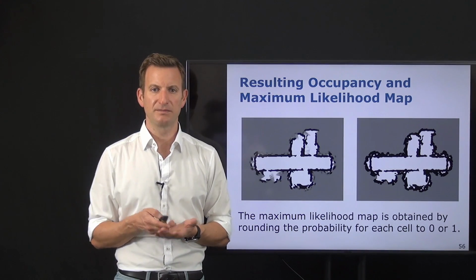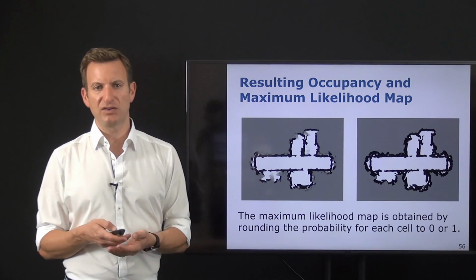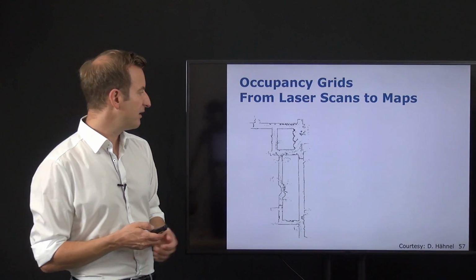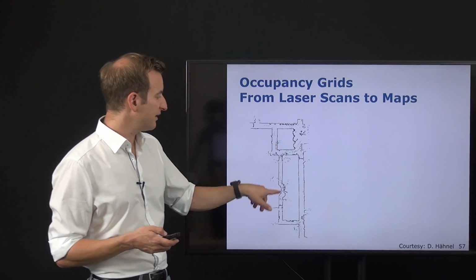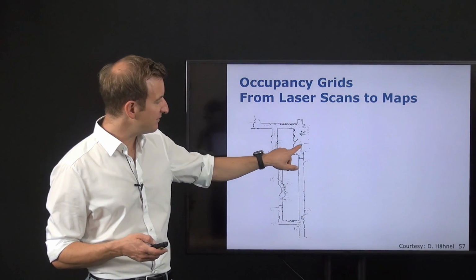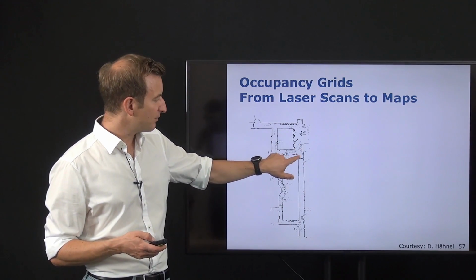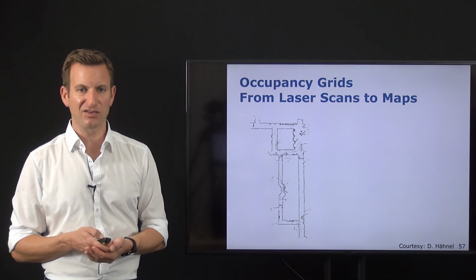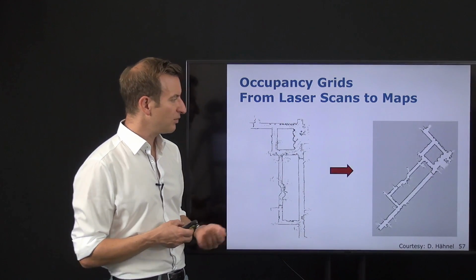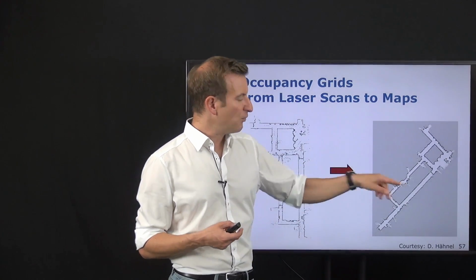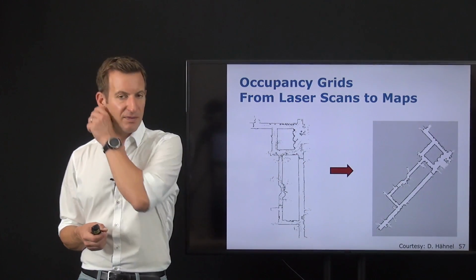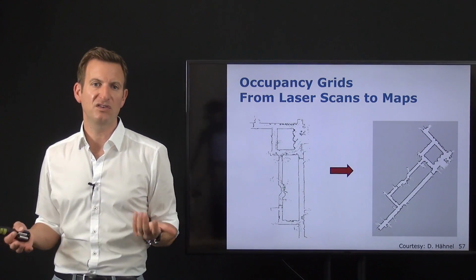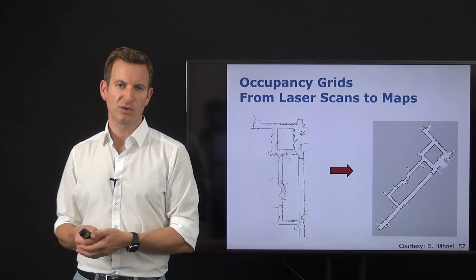Today we will most of the time use this with laser range scanners, so with this kind of step function model that I presented in the beginning. If you have sensor readings looking like this, so these are just the endpoints plotted, you can even see here that there are some sprinkles around. These were actually a person walking through those corridors while recording the data, so violating the static world assumption. But if you turn this into an occupancy grid map, you can see that those moving objects are often removed in this map because the person is moving through the environment, the robot gets multiple observations, so it sees a space once or twice as occupied and afterwards as free again.